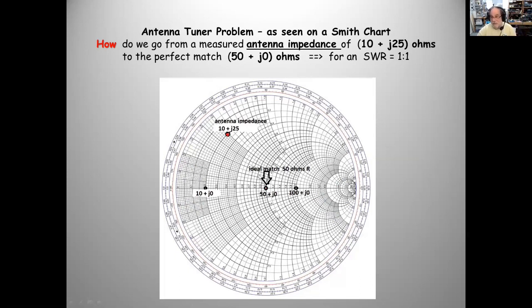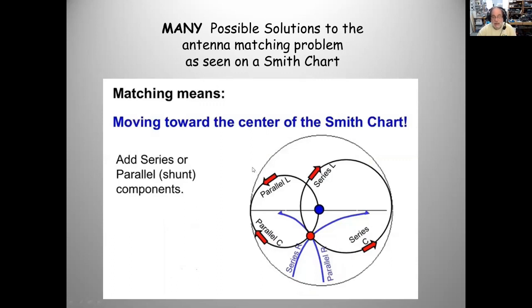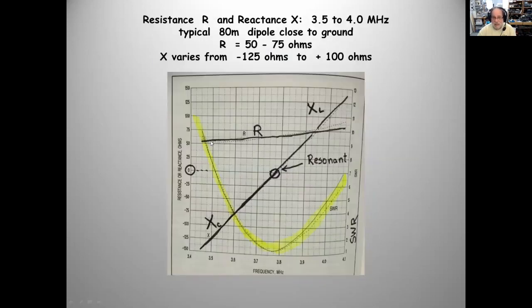It's electronic or something. So we have these devices called antenna tuners with parallel or series inductors and capacitors. And I don't want to go into the gory mathematics here. It's kind of interesting, but with an antenna tuner, I can get rid of this reactance in my shack, but not at the antenna, cancel the bad reactance so my radio never sees it. In other words, my radio thinks it's operating into a 50 ohm load. It's not. The antenna might be 150 ohm load with reactance, but my radio doesn't care.